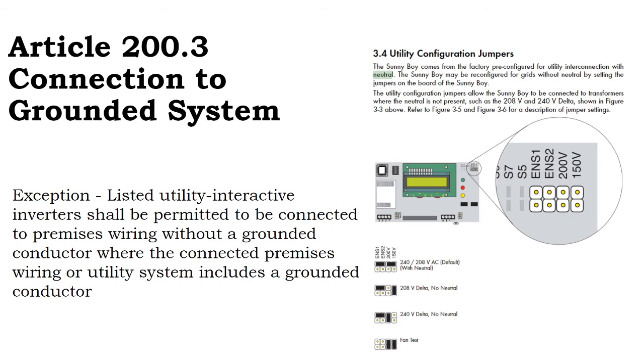So sometimes I'm thinking about small solar and how to incorporate a small solar project onto a site without much muss and fuss. And the answer is, well, there is that disconnect switch location where air conditioners come into the building. If you wanted to just throw a 4 or 5 panel system down on the ground with a small, even a cheap lead acid battery, just to provide some backup power to your AC or otherwise reduce your AC system usage, there are opportunities for grid tied, lower end, lower cost projects down on the ground that installers aren't even caring about right now.